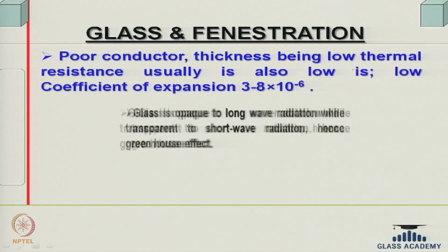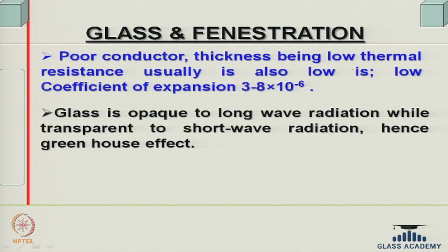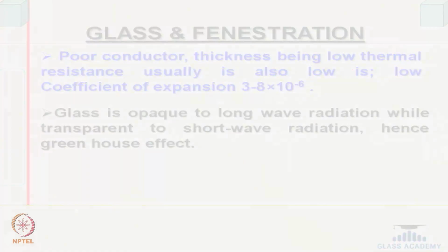So, the surface area receiving radiation and exposed to outside temperature, per unit volume, multiplied by the intensity of radiation received on each of those surfaces, and the glass area multiplied by the intensity of radiation there, this sum total of all the heat input that can occur through the envelope, divided by volume, because area and volume are related. Whichever is the least, that is the best orientation and shape.